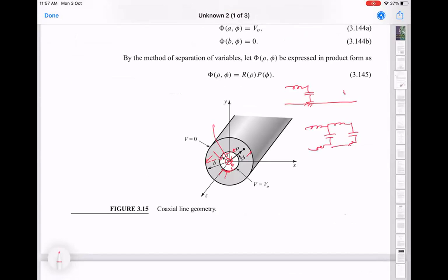Then the two sides are equal. But usually, in most cases where there is a ground definition, you will see that that conductor will be much bigger than the other conductor. So in coaxial, the center conductor is thinner, and the outer conductor has a larger surface area. If you think about the inductance of a section going this way for the outside shield versus for the inside shield, the inductance will be larger for the inner one because it's thinner.